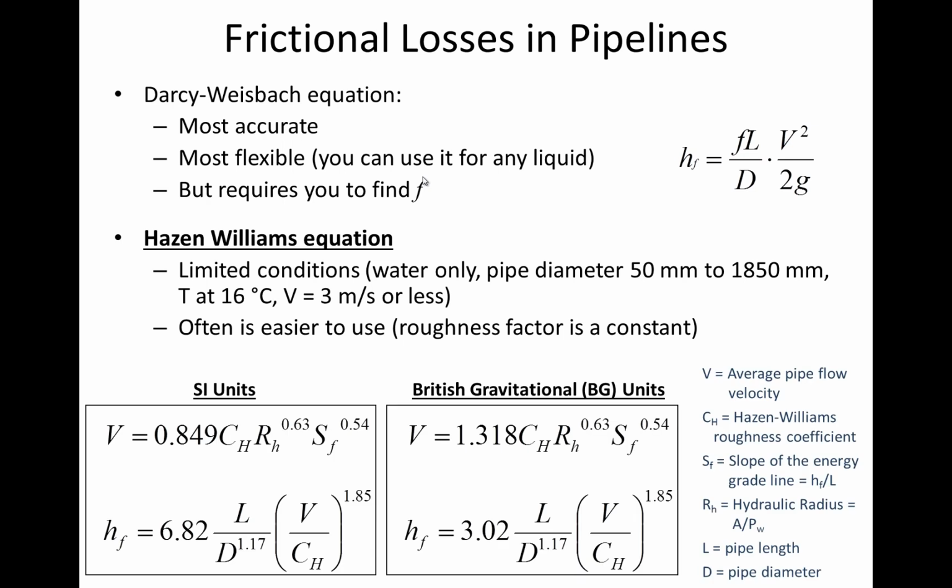So it's definitely easier to use the Hazen-Williams equation than the Darcy-Weisbach equation because the friction factor not only does not have to be calculated, but it's not an implicit equation like the Colebrook is. It can be expressed in two different ways. One form of expressing the Hazen-Williams equation is to find an unknown velocity for a certain pipe roughness that's known, that depends on the material that's being used to convey the flow.